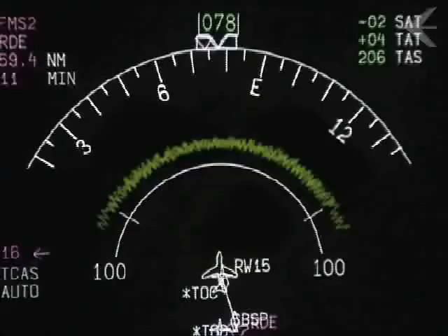The lightning strips that are incorporated into the radome body are very important, but they charge a price. The main emission beam has 4 other secondary beams. One of these reflects on the lightning strips and goes directly to the ground. When it returns reflected by the ground surface, it appears on the display as a green arc, and it is proportional to the conic rate of the radome. The narrower the radome is, the bigger the arc displayed will be. This is an airplane installation characteristic, not a radar failure.